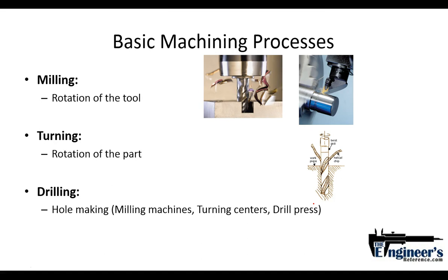And there are certain limitations to a machining process that all of these have in common. So all these have some things in common in spite of how different they are. And one of those is the component is dependent on being fixed in place. It has to be presented to the cutter, and it has to be rotated around, and it can only produce so much geometry at a time. So some of these alternative processes are going to get around that ability to do machining.